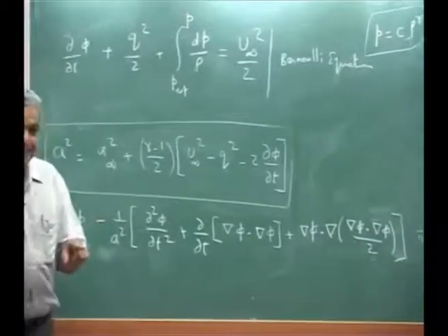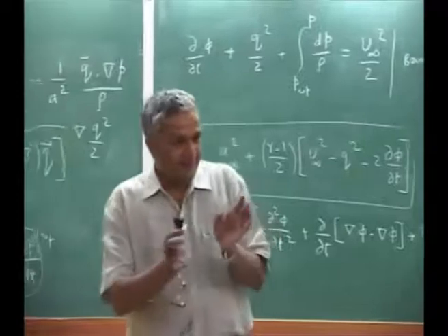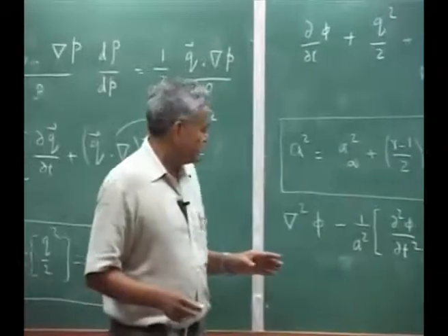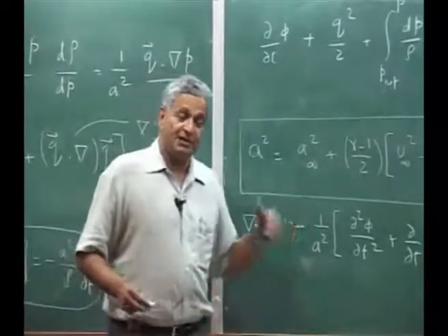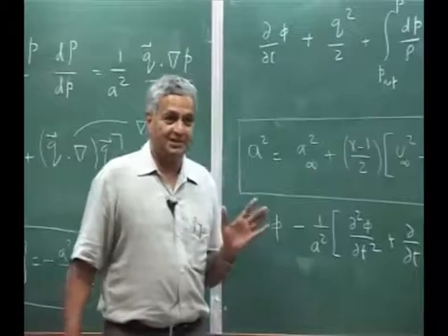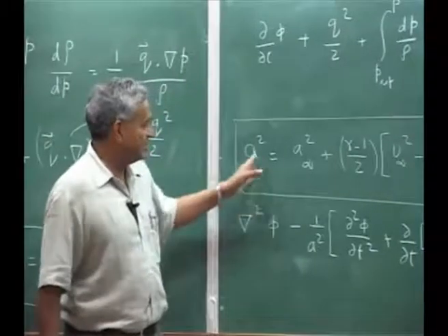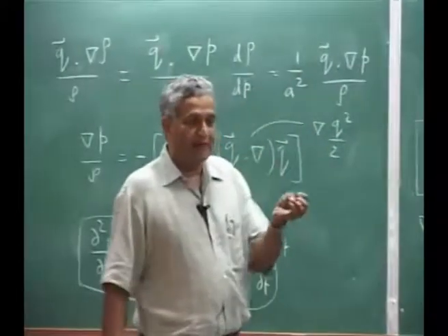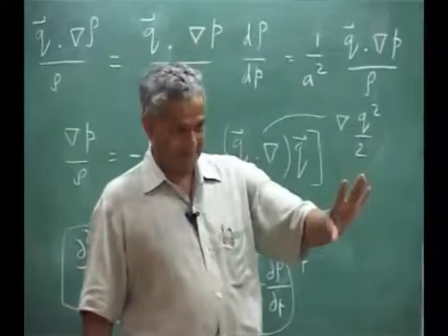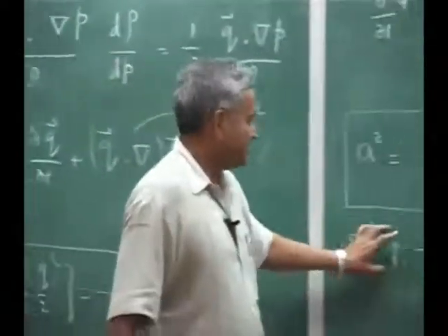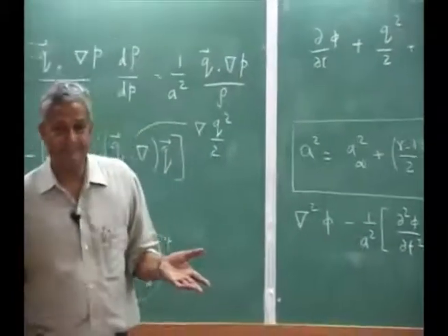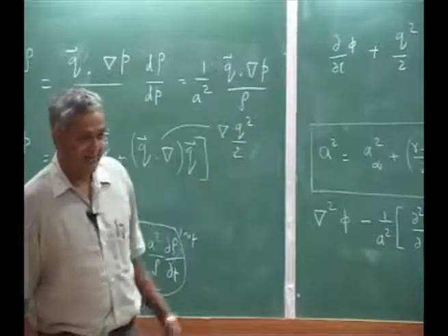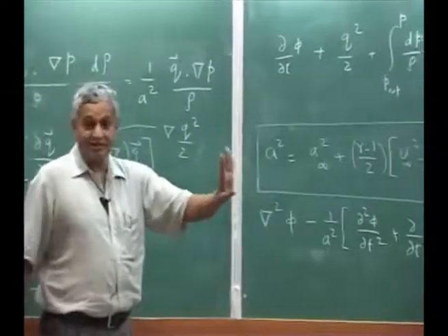That is why even in low speed, incompressible condition, if you assume, del square phi is 0 for unsteady flow also, but it does not matter. And then you have only phi, anyway A is gone, it is infinity. So your complete unsteady flow equation is governed by del square phi equals 0, that is a Laplace equation. Okay, whether it is steady, unsteady, it does not matter, you have the solution. You have this equation. Only thing is you have to get now the boundary condition.